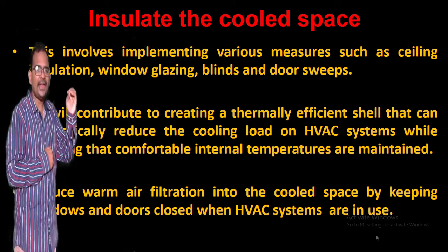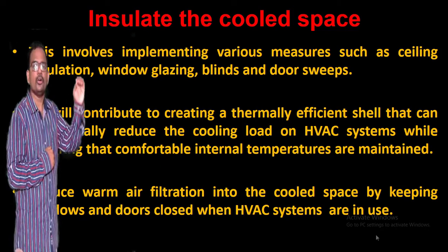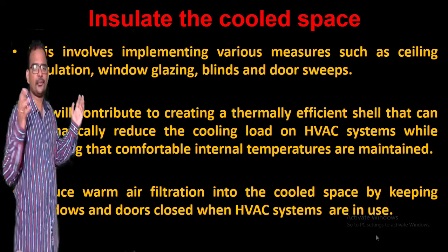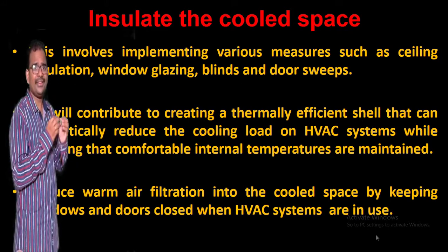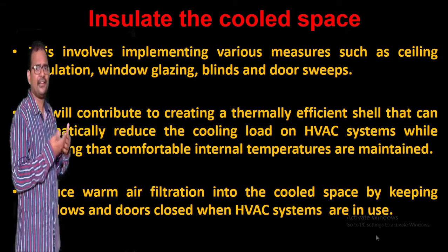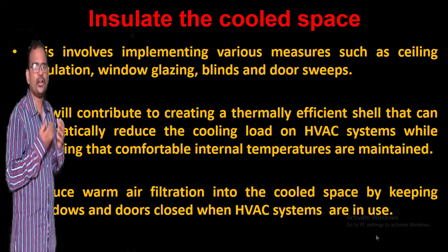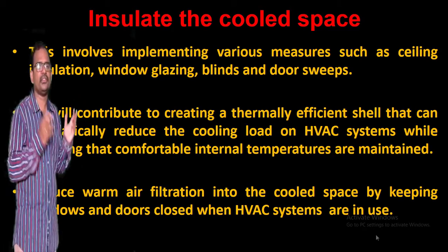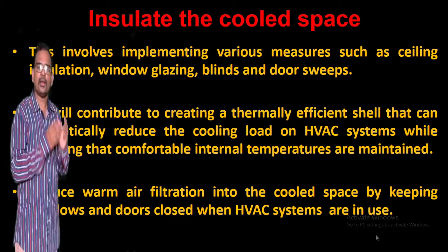Reduce warm air infiltration into the cool space by keeping windows and doors closed when HVAC systems are in use. So when we insulate the room by means of ceiling insulation, window glazing and blinds etc., we will be able to reduce the cooling load. As well as if I can close the doors and windows while the HVAC system is in operation, it will also reduce